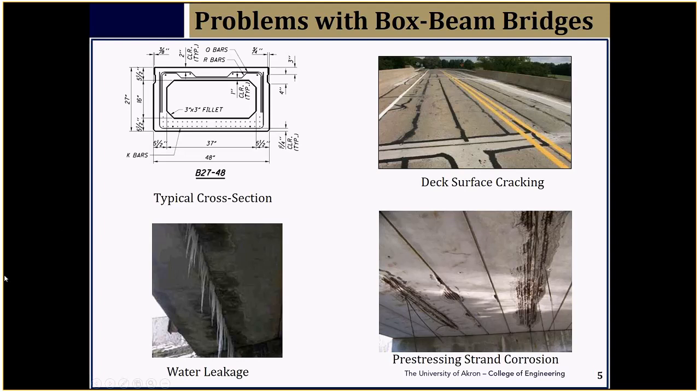I should have provided an enlarged view of this, but the distance from here to here, which is the recess of the keyway, is 3/4 of an inch. With the top opening here, we have 3/8 of an inch on one side, so two sides will give us 3/8 times 2, that's 3/4 of an inch.